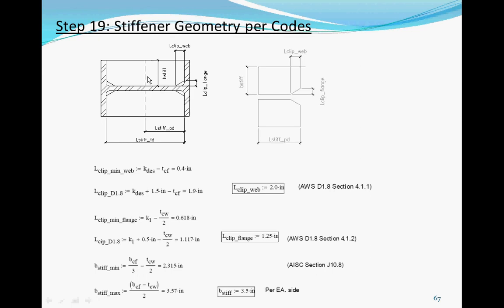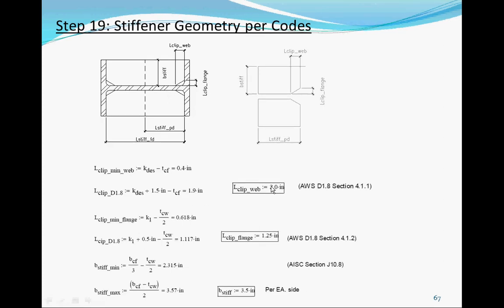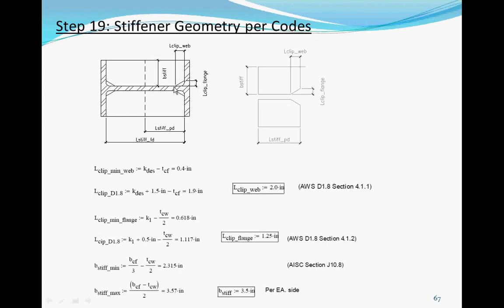So if they do that, in this area there's some built-in residual stress. So if you weld to it, you might crack it, and they have seen cracking in some cases. So they discourage welding to the K area, and that's why the 2 inch compared to the 1.5 inches for that clip. Okay, so they clip this much like that, and then you start welding. So you don't weld it to the K area region.